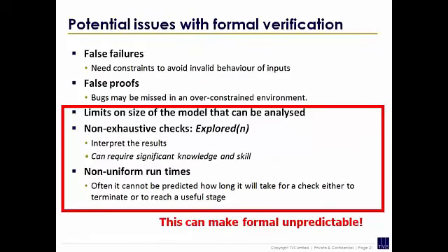And the potential issues are limits on the size of the design you can do. If you get explore, then you don't know what it means, and it's non-uniform runtime. The good thing about simulation, if you look at these simulations on our depth first search, normally they all run for about the same amount of time. You can predict how long your simulation is going to run, and normally I know these simulations are going to take 5 minutes, and I know over 24 hours, therefore we can run 1,000 simulations, and we know what we're going to do. And what can happen here is formal can take a minute here, then 5 minutes, then 10 minutes, and this may take 2 days, 3 days, 4 days, 5 days. So it's unpredictable, and managers never like unpredictability.